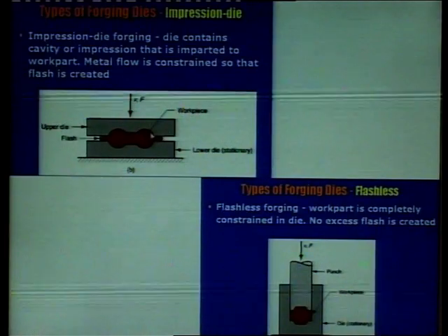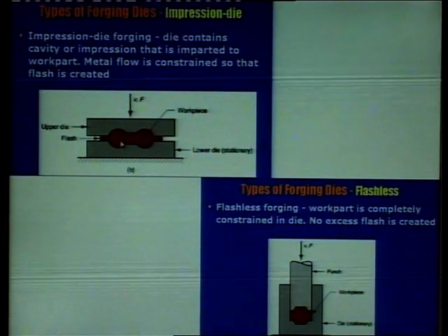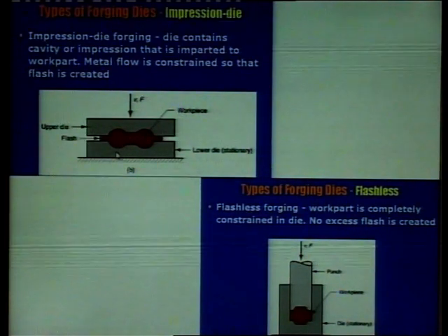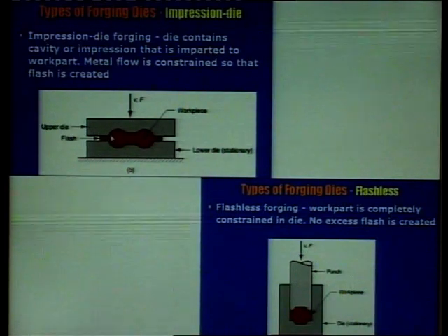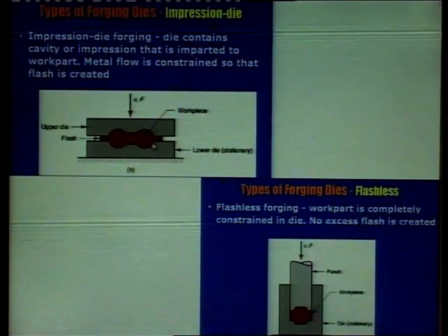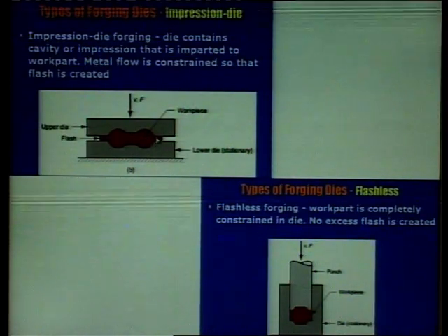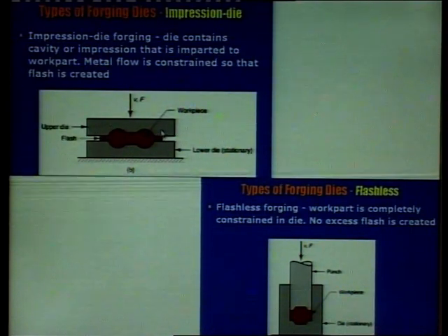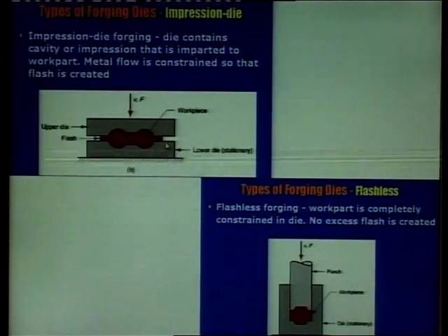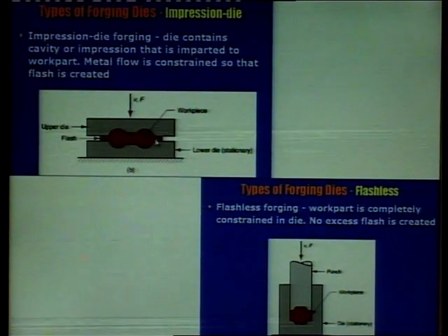The raw material may be flat, but we control the shape of the component coming from the die, while at the same time some extra material flows out of the die and does not allow it to close. This is called flash.